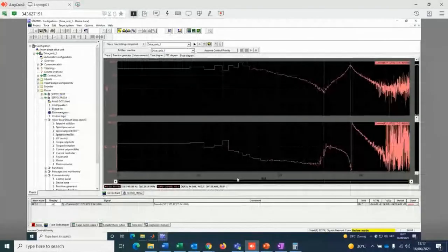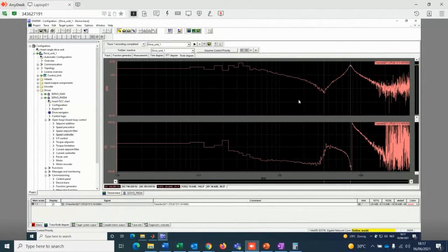Okay, now we go again to starter. So this is the Bode plot for the setup I am using. It is similar to the one that you got when you did the second hands-on. So the idea here is to identify the resonance frequency first. So we go to the cursor here, we pick up the resonance frequency. Here at the bottom of the screen, we can read the value for that point and the frequency.